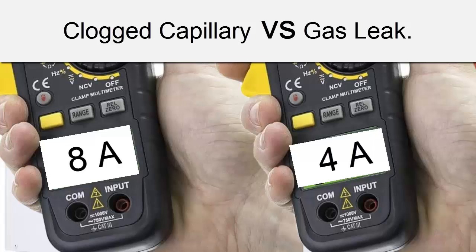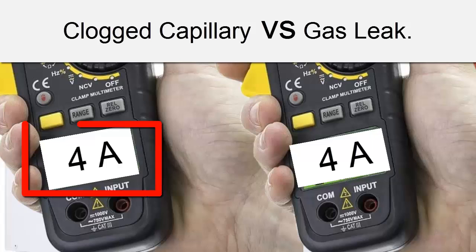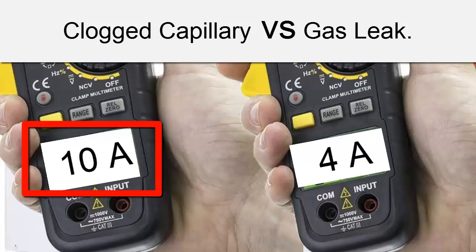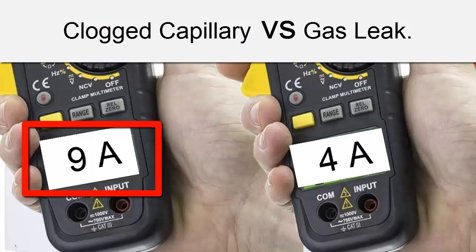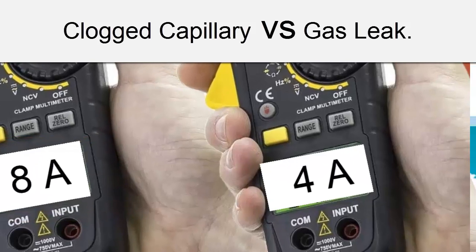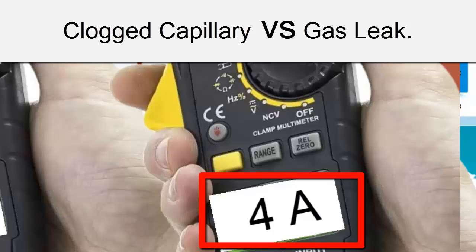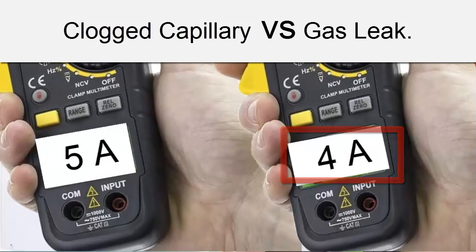7. If the equipment failure due to freezing of the thin pipe is solely due to a lack of refrigerant, the amperage consumption will be low all the time, even shortly after turning on the equipment. In this aspect, measurement can be taken with an ammeter clamp. Additionally, when there is a lack of refrigerant, freezing or cold does not concentrate specifically in the capillary tube.